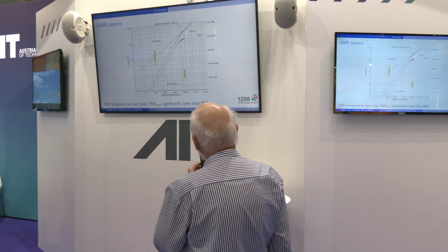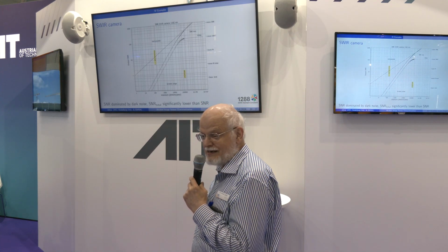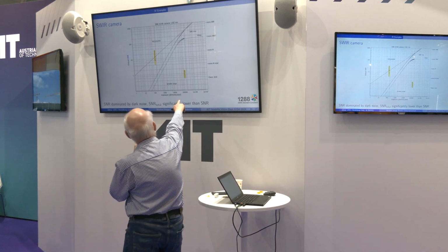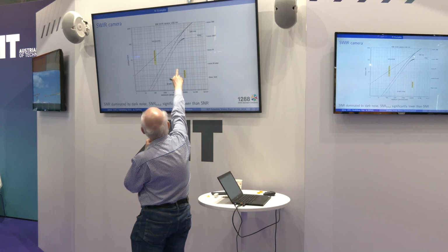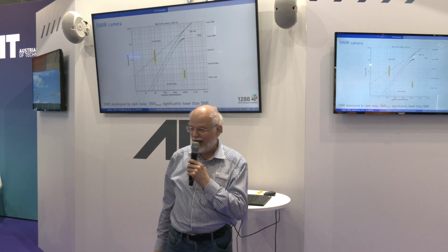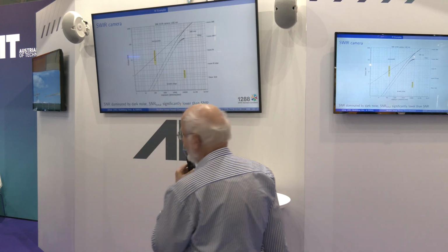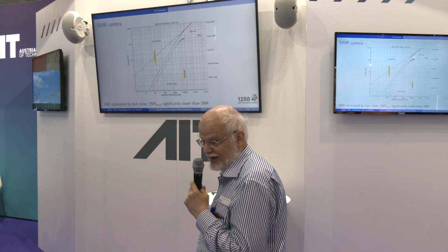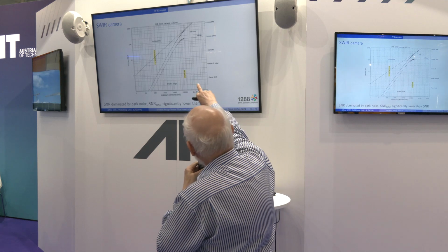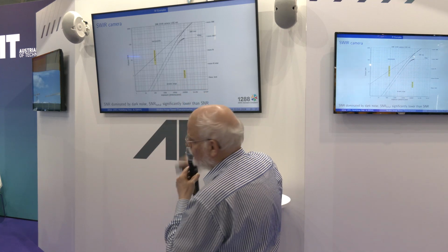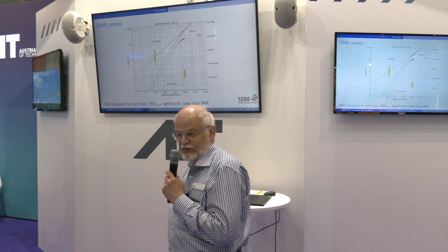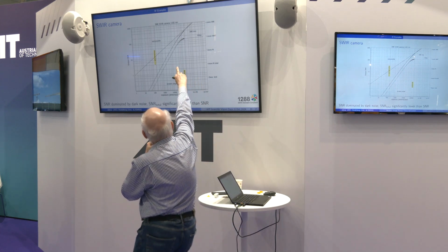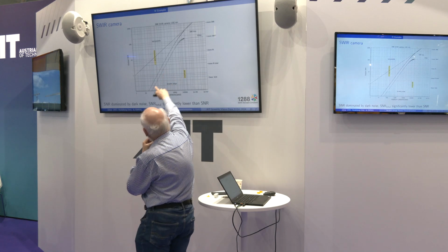If you look now at a sphere camera, it's completely different. First, you have a much higher saturation because you typically have larger pixels. It's now not 10,000s, but 100,000s, more than 10 times. And therefore, although the highest SNR is not 100, but rather 400 in this example, so 4 times better, the curve of the measurements is much steeper.